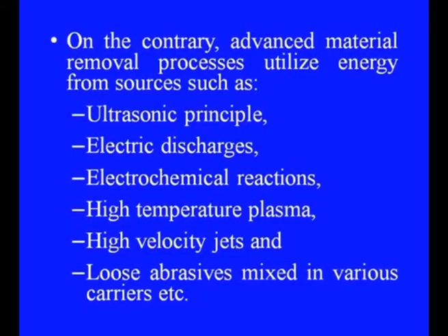This is one of the most important issues in this case, where there is no physical contact between the so-called tool and the work material, yet the machining is done very effectively. The advanced material removal processes utilize energy from sources like the ultrasonic principle, electric discharges, electrochemical reactions, high temperature plasma, high velocity jets, loose abrasives mixed in various carriers, and other electromagnetic energies.